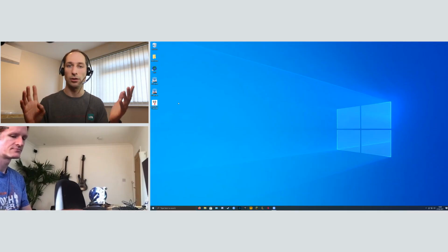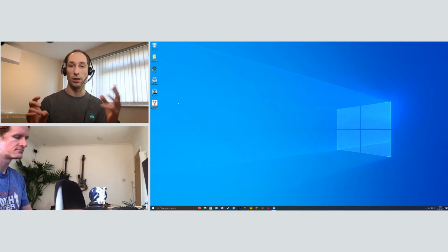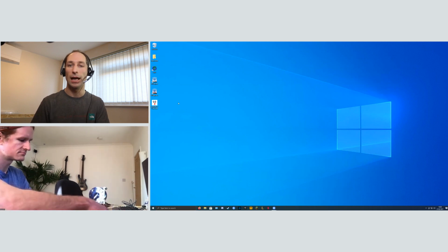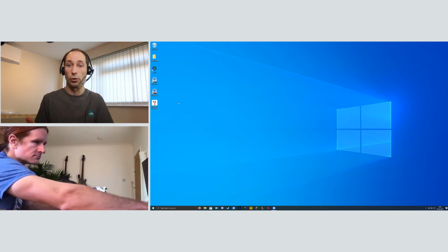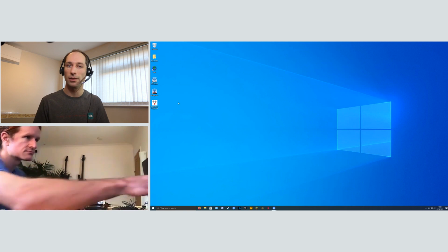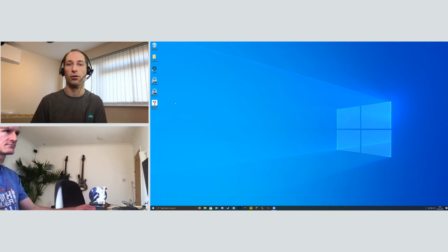Very good. Great. So that's all of our soldering done. We're now ready to head over to the computer and the radio and see if we can get them talking to each other. Great. On the computer, you can first of all plug in that USB to serial converter that we had, and we'll find out whether it's showing up, whether it needs drivers, and what COM port number it's gone on.